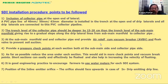The most important thing over here is to encourage the farmers to use water meters, because if there is a drop in the flow or a drop in pressure, then immediately we will come to know that there is some problem with the system lying underneath the soil, which is not physically visible to us. And in the case of an inline emitter system or a flat emitter system, the orifice typically should be facing the top and not the other way around, so that we avoid the roots searching and coming into the inlet of the emitter.